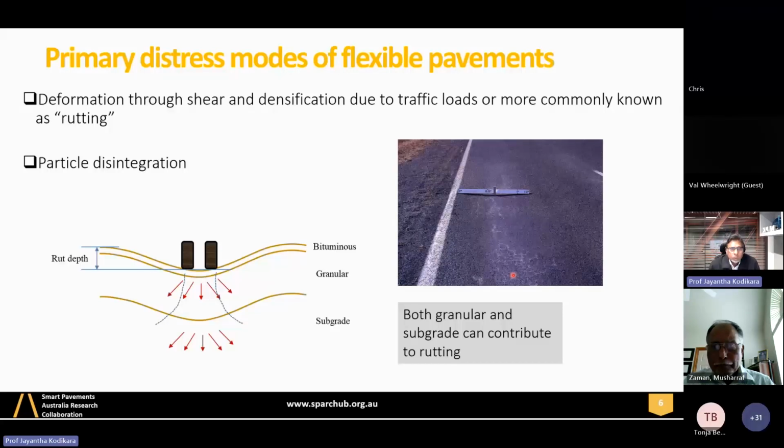Yes, because we have calibrated our curve. We have three parameters in our equation. One is the initial density, then the moisture degree of saturation, and the stress. Stress also we simplified. You can go to deviatoric and mean stress and so on, but we simplified to one stress ratio, because otherwise you will have too many parameters.